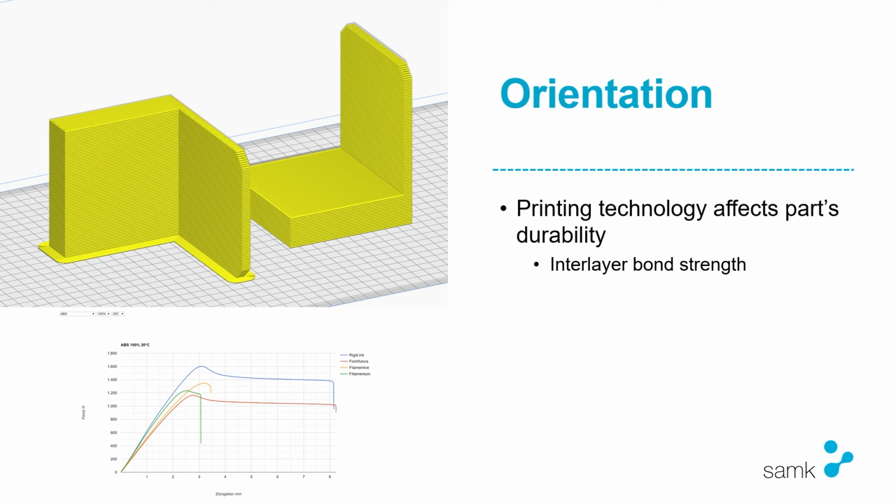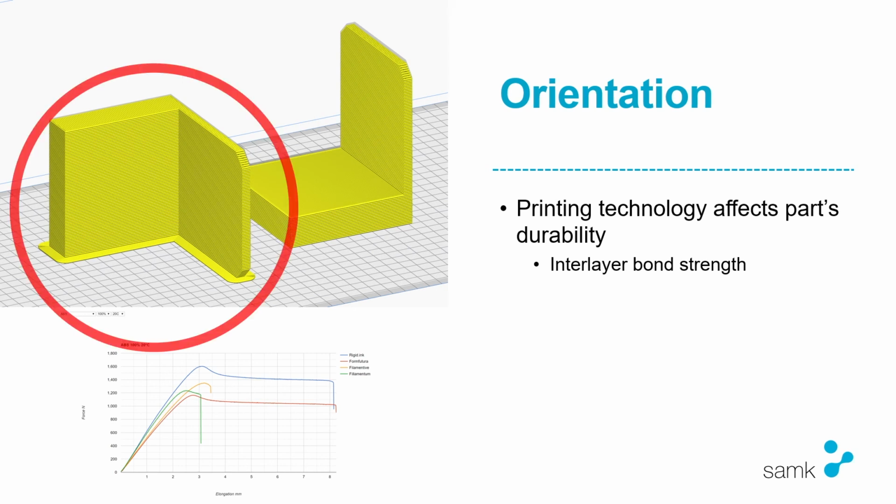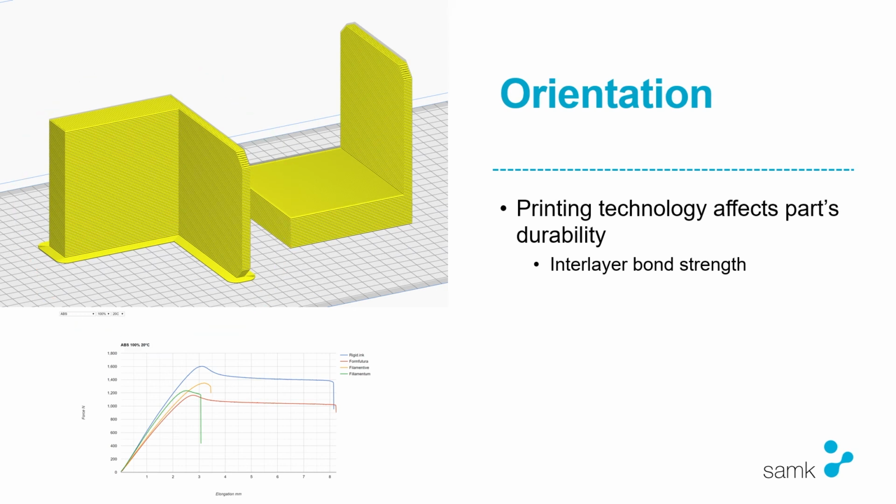will snap at the root of the connection of the thicker part and the thinner part, because the thinner part will have a serious durability problem since it's printed in that direction. It affects the strength of the part. It doesn't hold up much in that direction. But if we turn it 90 degrees to the right, like in the left image, it will have considerably more strength. It can withstand more pressure pushing on that thinner wall.